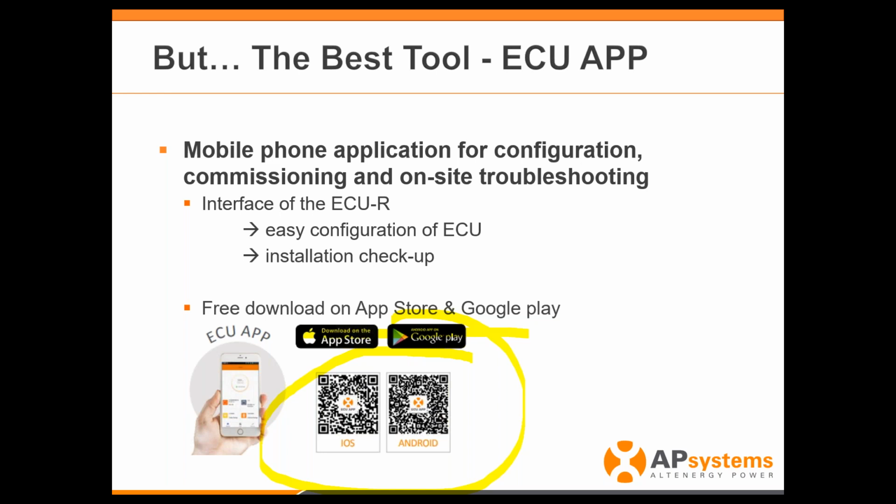The nice thing about this is it gives you the ability to configure the system, commission it right there on site, do the troubleshooting, and do an installation checkup. Before you even leave that site, you're going to know that you've made good DC connections, that you've put the serial numbers into the ECU, and that you've got AC to the inverters and power production. It also lets you take a screenshot of that and use that as your report card for the day.